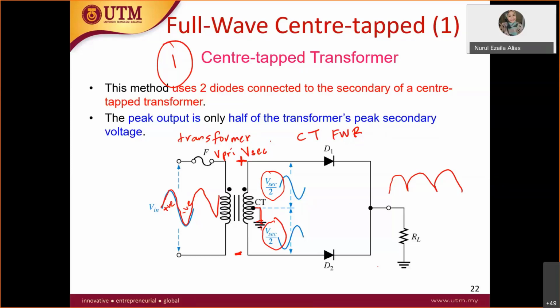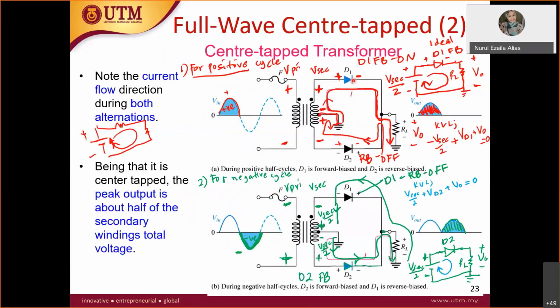Lei Yong asked what happens if the diodes are pointing in different directions, for example the upper one to the right and the lower one to the left, and whether this connection is possible. It doesn't matter what the connection is, as long as you can find a current path from input to output that makes the diode forward biased. That is possible.